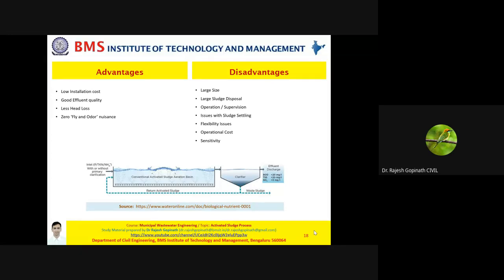Unlike trickling filters, there is very little head loss. If you remember, in trickling filters, you had a rotor system, a distribution mechanism. You had to pump the wastewater to a significant height and then make it fall down by gravity. Also, in trickling filters we had issues of bad odor and psychoda, but here the system is aerobic in nature.